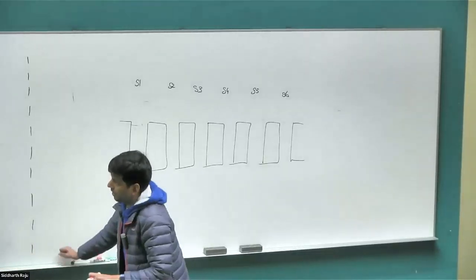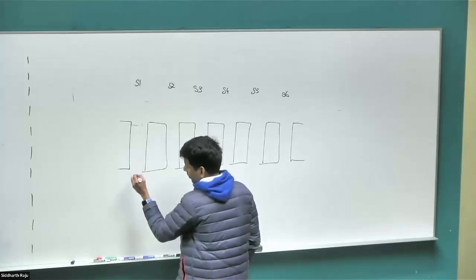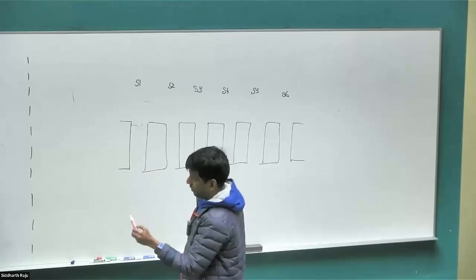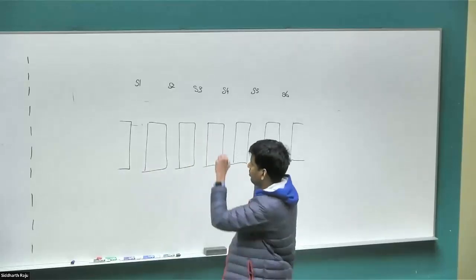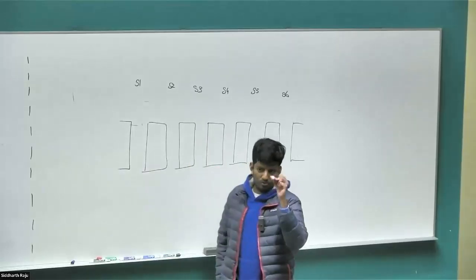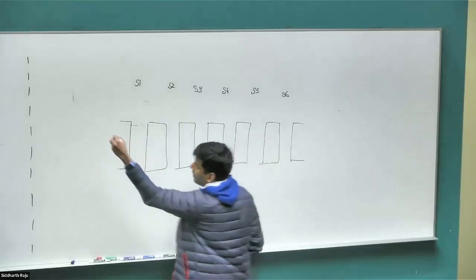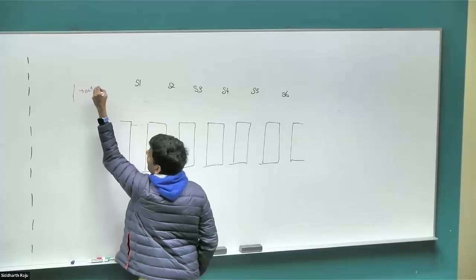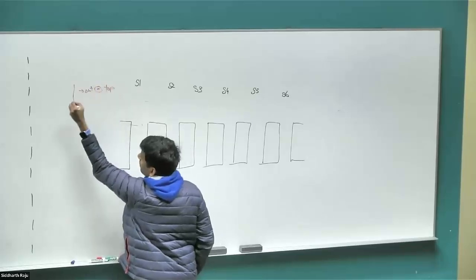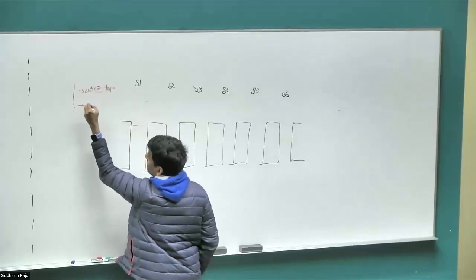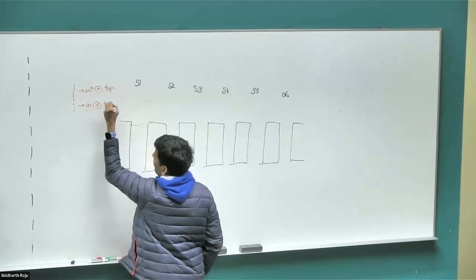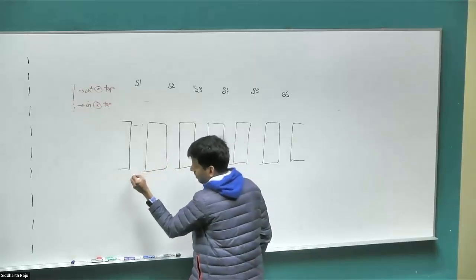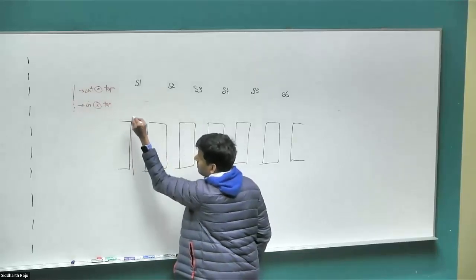Okay. So let's start off with our first conductor. Whenever the conductor is coming out on the top layer, I'm going to use a solid line. Whenever the conductor is going into the top layer, I'm going to use a dotted line. That's the convention I'm going to be using. So solid is out on the top view, and dotted is in on the top view, right? So the first conductor is coming out of the top in slot 1.